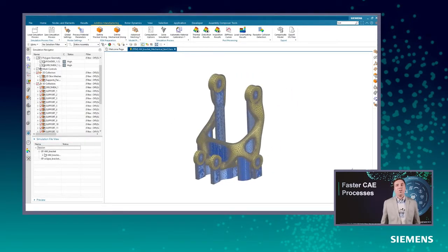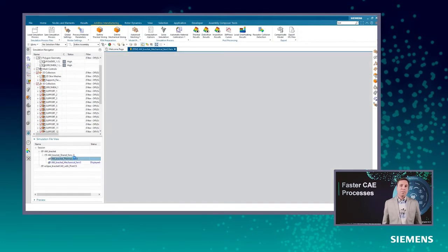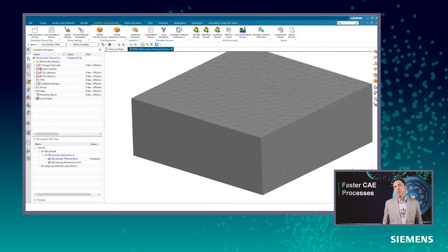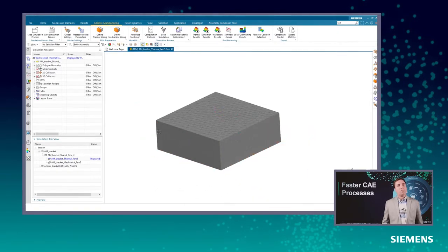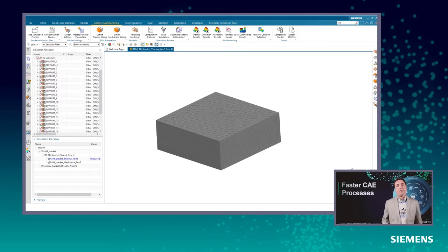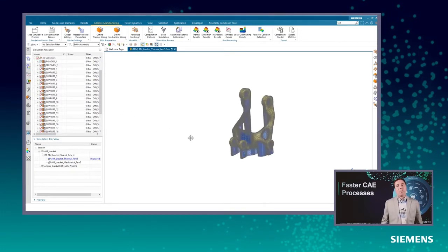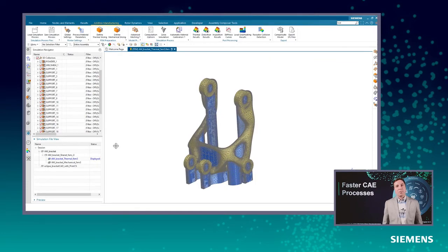However, the trade-off to using exact meshing is that the meshing procedure can be challenging for complex parts. In Simcenter 3D 2021.1, the automatic meshing procedure was improved to better deal with model complexity. If for any reason the meshing fails, you can now manually defeature idealized geometry, correct mesh mating conditions, and modify CAE geometry and control mesh settings using the advanced meshing for additive manufacturing.